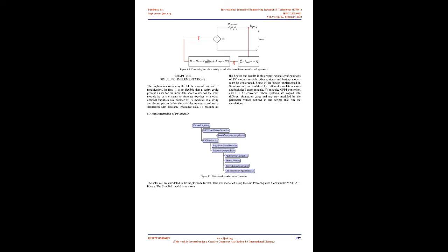Because day by day the demand for electricity is increasing, and that much demand cannot be met by conventional power plants. Also, these plants create pollution. So if we go for renewable energy it will be better, but throughout the year the generation of all renewable energy power plants varies. A grid-tied PV system is more reliable than other PV systems. No use of a battery reduces its capital cost, so we go for the grid-connected topology.